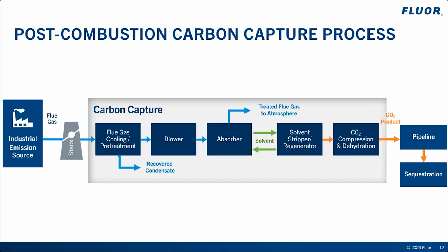For CO2 products being sent for disposal via sequestration, this water specification is set to avoid hydrate formation in the supercritical CO2 product. The dry CO2 from the dehydration unit is sent to the final stages of compression and cooled to meet product delivery requirements.